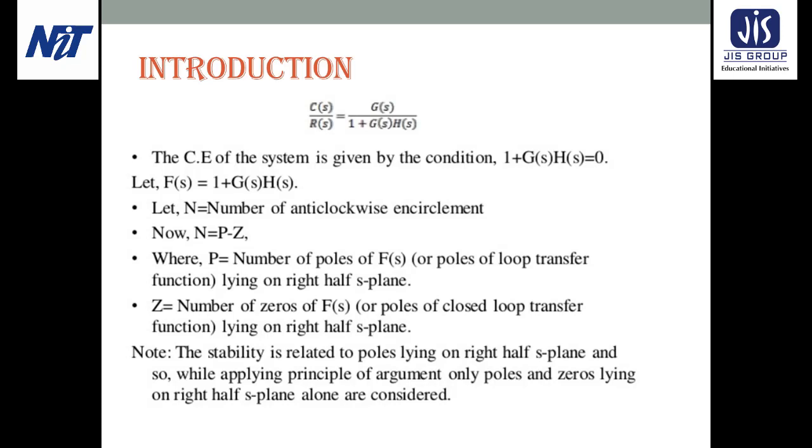So first we have started with the frequency response. Now the frequency response of a linear time invariant system is independent of the amplitude and phase of the input test signal. The transfer function of the system can be obtained from the frequency response.